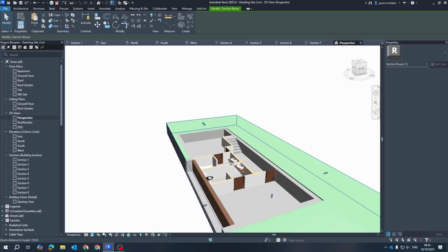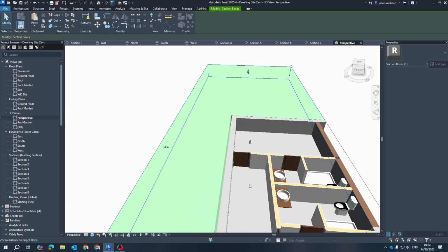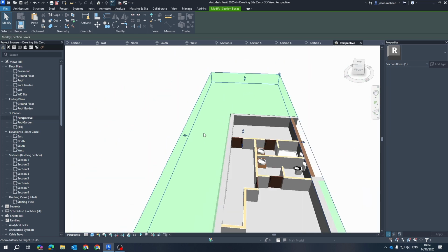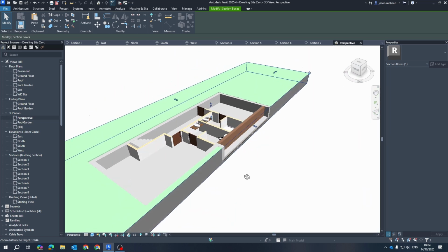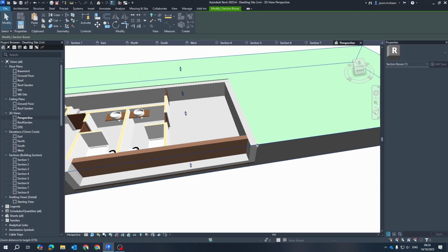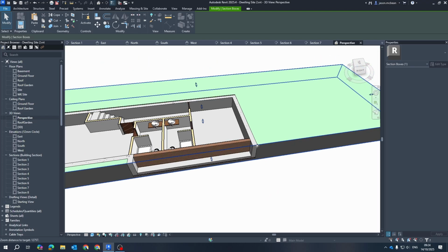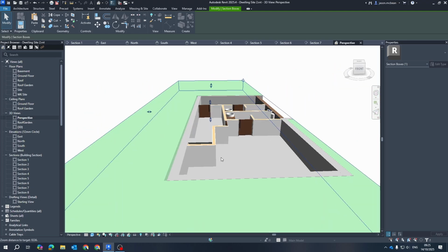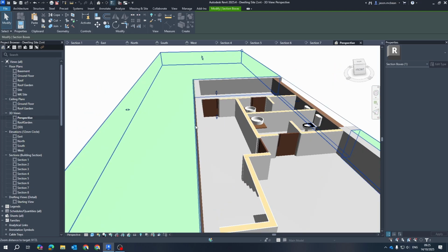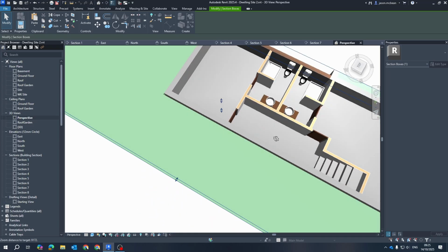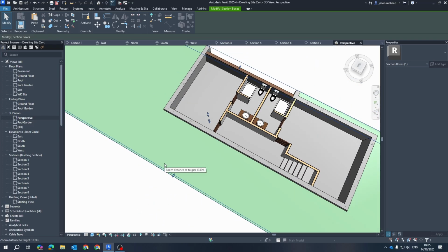So we cut into the basement, for example. You see I've left 100 millimeters around my building so that they'll knock steel sheets into the ground to form a permanent shuttering to retain the earth, because your neighbors you can't dig away. So you knock steel sheets in and then you start excavating and then you keep hammering those steel sheets in. It's a method that they use to create basements, and you can see that that's why I've left that gap, because that's where the steel sheets will go.